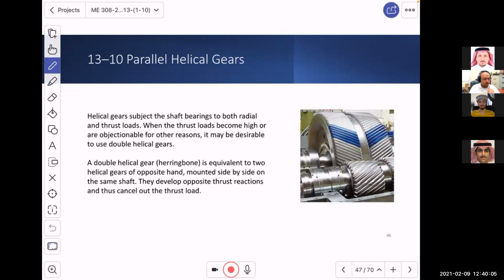Noise, I don't care about noise because I am not going to end up buying very expensive bearings and deal with this thrust load and so on. No, although we taught you everything on how to deal with the thrust load in terms of bearings, you can actually deal with it within the gearbox itself, like this.